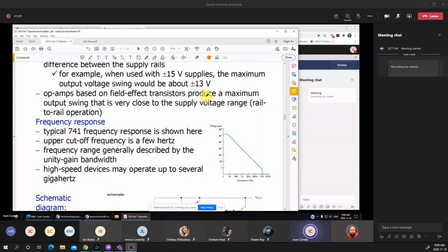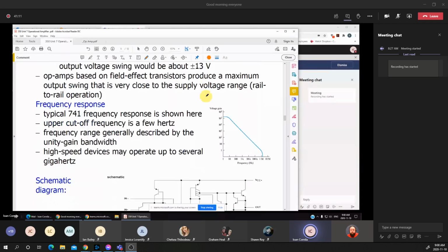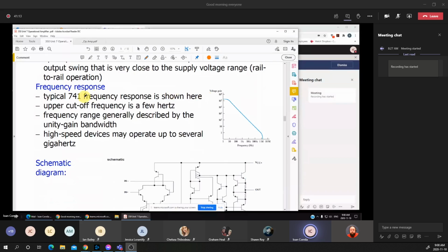In terms of the frequency response, if I plot the Bode diagram, or the frequency response for the op amps, you notice that at low frequency it has a very high gain, which is 10 to the power 6, or in this range in dBs.